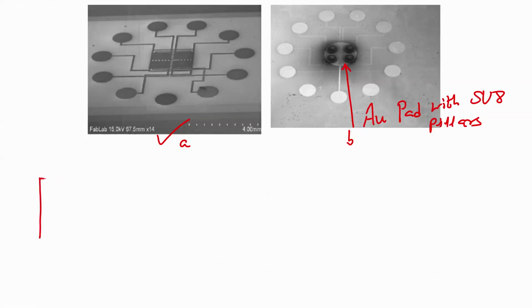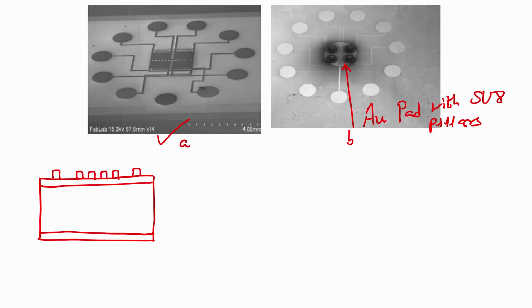So, what does it mean? That we had an oxidized silicon wafer on which there was a micro heater, on which there was insulator, correct, on which there were interdigitated electrodes, on this there was piezoresistive material, right.